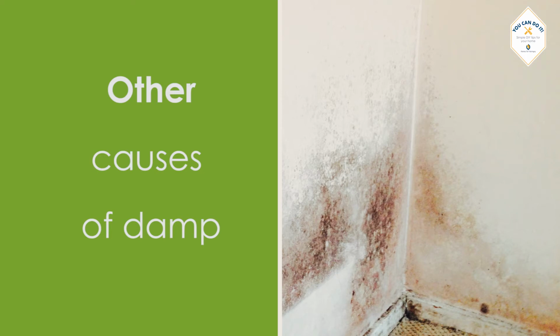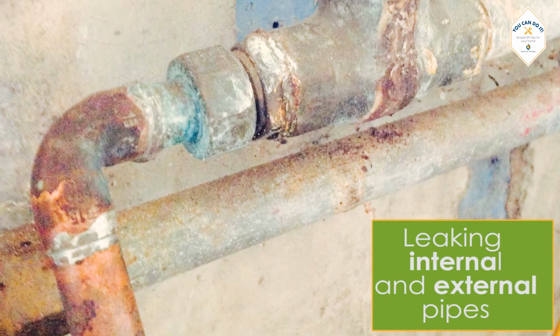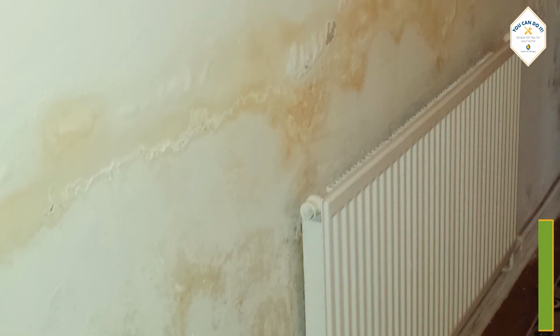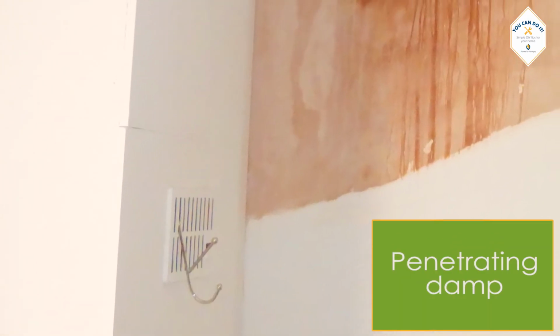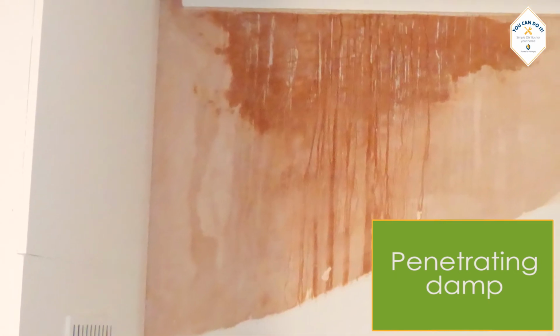Other causes of damp. Damp in walls and ceilings can be caused by condensation, but there are other causes of damp such as leaking internal and external pipes, rising damp which is caused by moisture from the ground into the walls of buildings, which results in structural damage. Penetrating damp is generally caused by a problem with the building, allowing rainwater to penetrate through into the home.